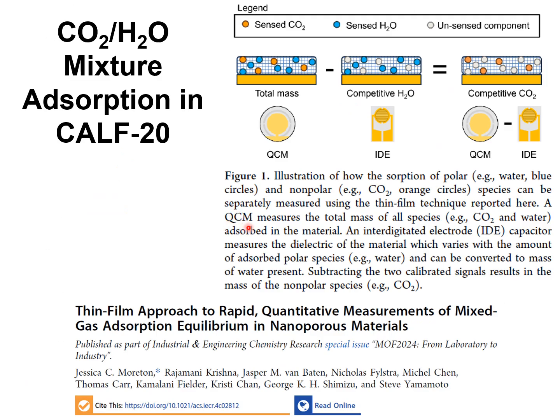Researchers from Matrix Sensors Incorporated in San Diego, California, have developed a novel technique that measures mixture adsorption equilibrium using thin films of sorbents deposited onto sensitive micro-electromechanical system transducers, MEMS. This technique is fast, requires very little material, and enables real-time monitoring of binary gas mixture adsorption in MOFs and other nanoporous materials.